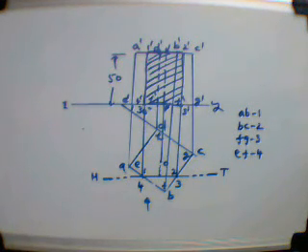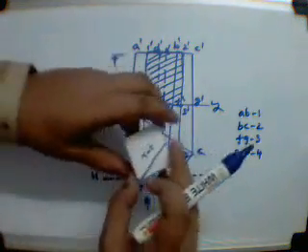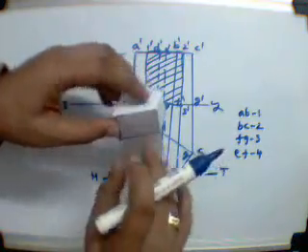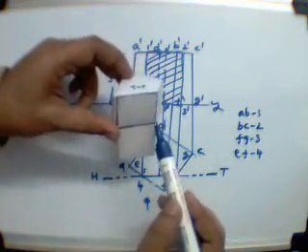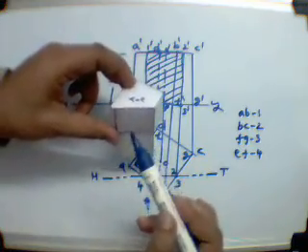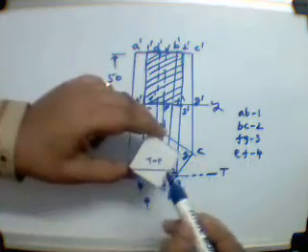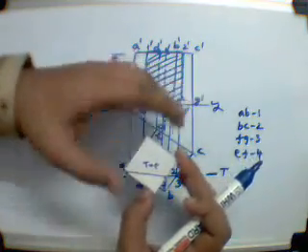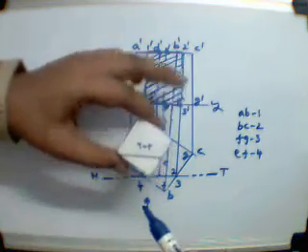Now I will show these 4 points on the model. Okay, the invisible point 4. So now on this section, this is 1, 2, 3, 4. With the help of these 4 points, I will represent the section in the front view. Now observe this. This section is parallel to VP. So automatically when you are seeing like this, you will get the true shape of the section in the front view.